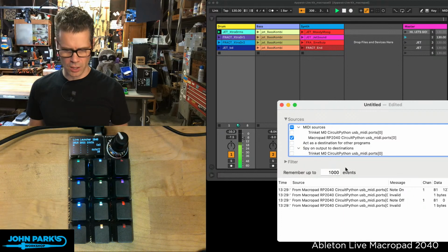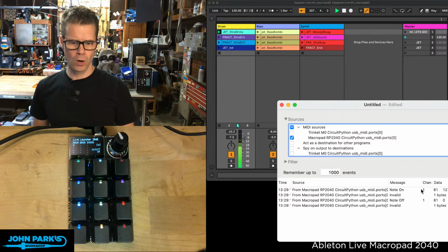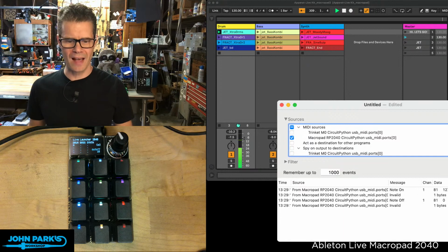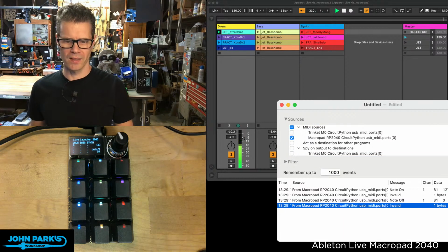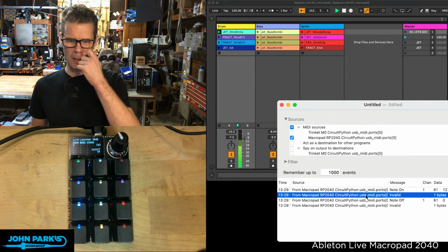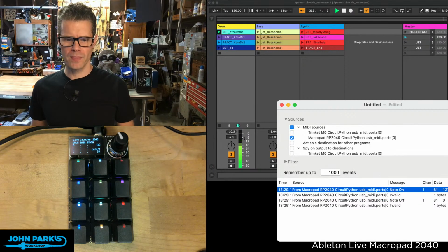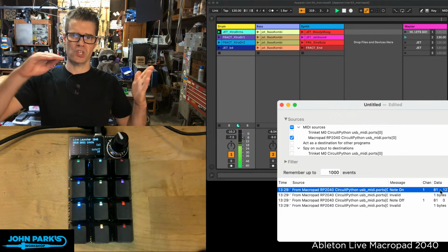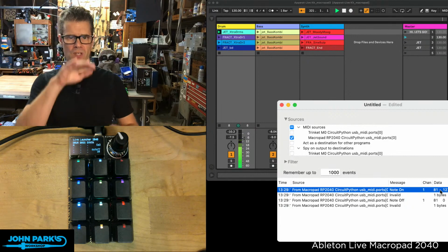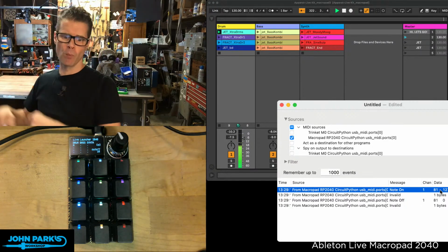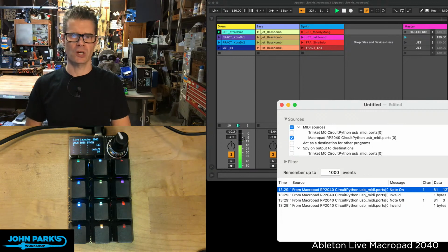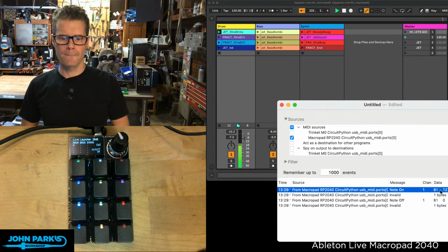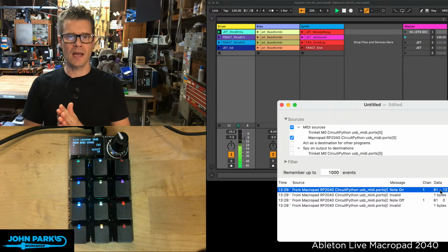What you can see here is it sent two messages. Ignore these invalid ones. We have an extra byte right now that's being sent in USB MIDI. This is being fixed, I think, in TinyUSB. The two messages that are being sent are note on over channel 1. MIDI has 16 channels. The MIDI note numbers exist from 0 to 127. Those typically represent the pitches on your keyboard or piano, the musical pitches. In this case, though, that's not how it's used.